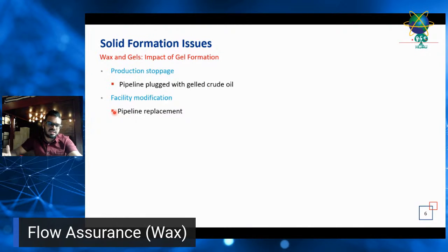I will show a case study later. It's from one of the oil fields in Africa. I was actually attached to this project, and they also faced this particular issue where the whole pipeline got gelled because they did not pig the pipeline frequently. It is a very highly waxy field.